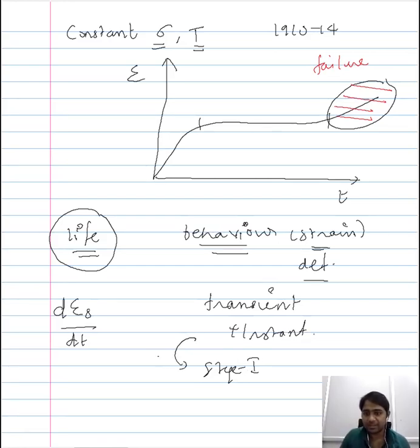In a similar manner, the life of the material as a whole is largely dictated by the duration the material spends in the steady state condition. Now, after the steady state condition, when the material begins to deform excessively at a higher rate, that corresponds to the tertiary stage. Generally, during a creep test, we stop the testing at that point. We will not allow the material to fail, because the strain introduced during stage 1 cannot be avoided in an application.